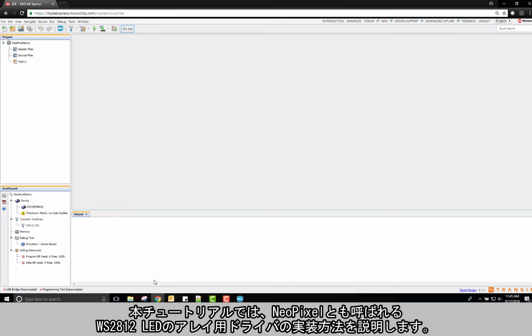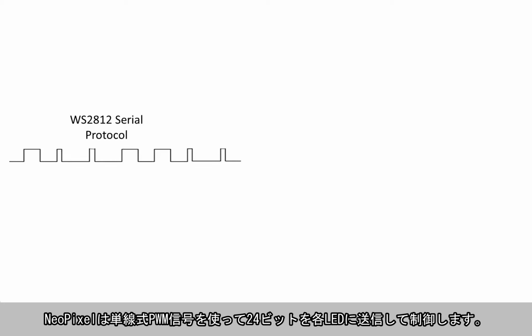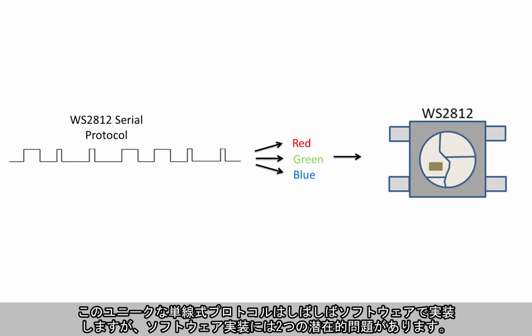In this tutorial, we will go over how to implement a driver for an array of WS2812 LEDs, otherwise known as Neopixels. These Neopixels use a single wire PWM signal to pass a total of 24 bits to each LED in order to control them. These 24 bits are composed of the red, green, and blue, or RGB, values of each LED. This unique single wire protocol can often be implemented in software.